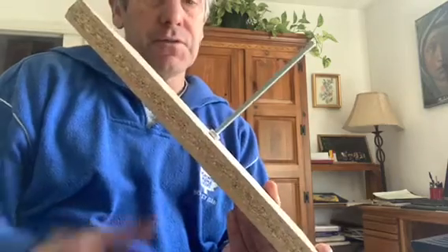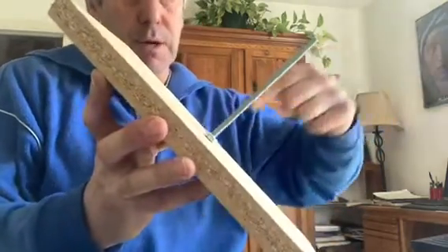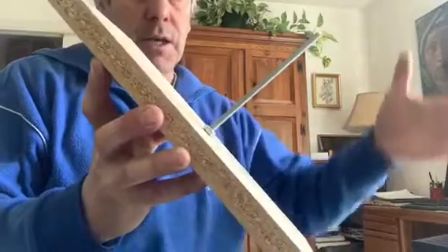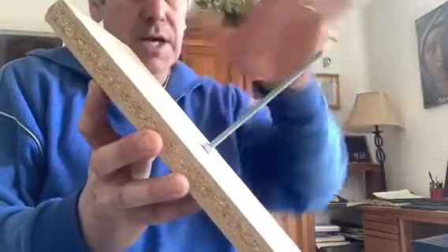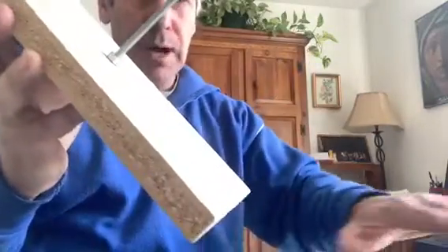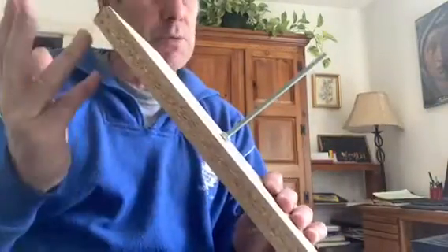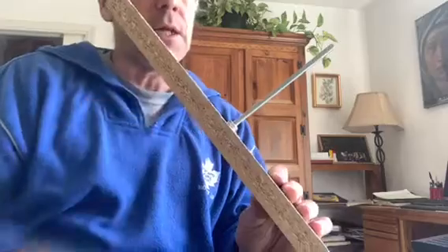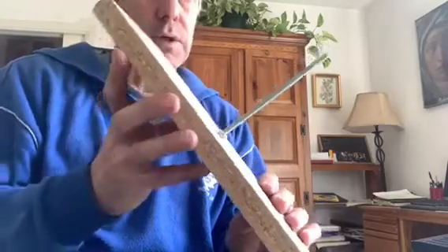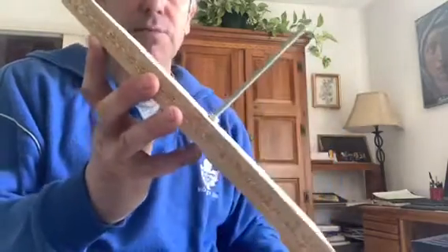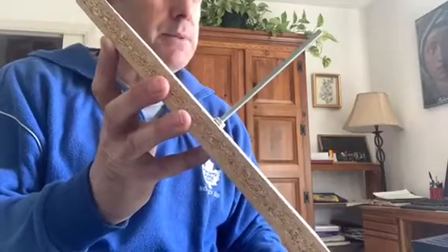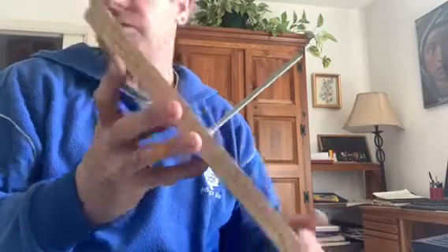So on a tilted surface, again, what we said is that there's going to be some direct radiation coming directly from the sun. There'll be diffuse coming from the sky dome that's hitting there. And then the ground in front, there might be some reflected that comes and hits that surface. So we need to figure out all three in order to determine the total incident radiation, say in watts per meter squared or BTU per square foot on that surface.